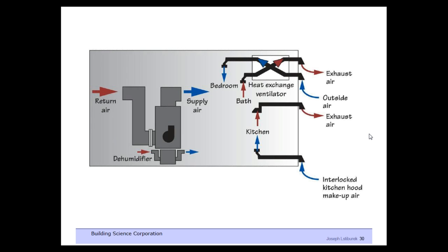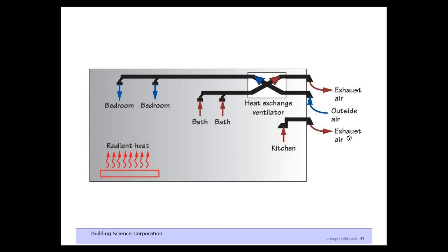Even with an ERV, a dehumidifier is going to be necessary because an ERV does not dehumidify. It maintains humidity but doesn't create the dry conditions. So the air conditioner provides the cool, the dehumidifier provides the dry, and the ERV maintains those conditions. There's a lot of misunderstanding of what an ERV is capable of doing versus not doing.